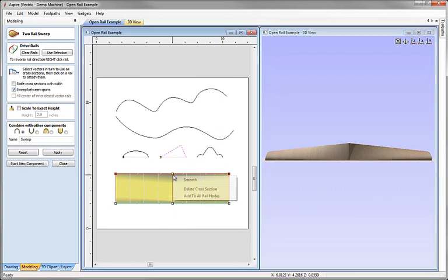Again, if we wanted to, I could right mouse click, choose the smooth option, hit apply. Now it'll smoothly flow through the middle, but it's not trying to smoothly flow through the end. So that's just going straight up from there, then smoothly through the middle and straight down to there. If I right mouse click and choose smooth and apply, now again we can see subtly this goes straight up and then smoothly through there, then down and smoothly through there as well. So at this point it's effectively going through that in a horizontal direction.